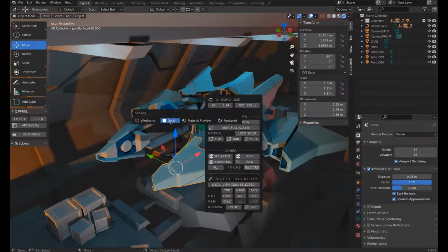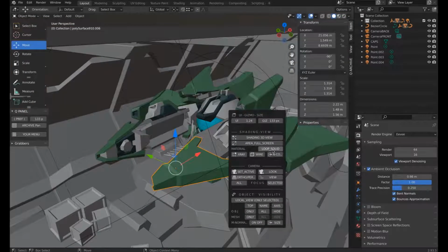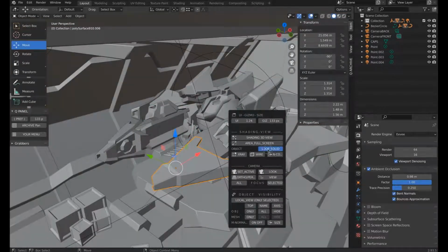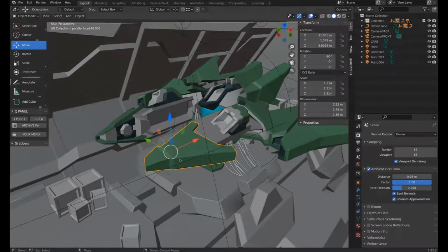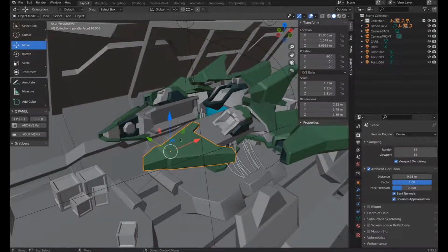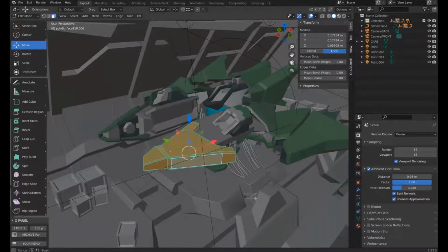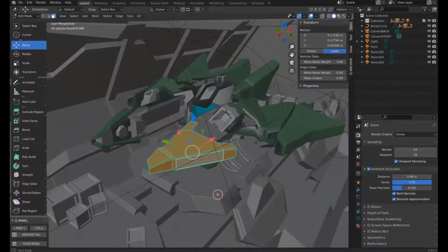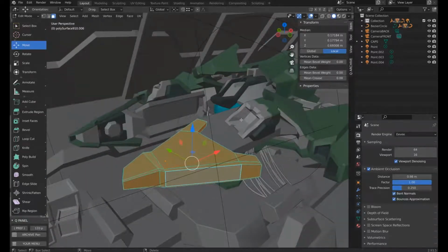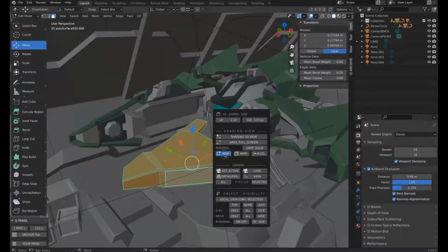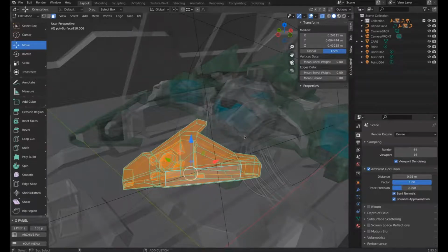Let's go back to the solid view to use the loop solid. Then we can see the X-ray. Blender lets you select only what you can see. So if you go in edit mode and try to select something, you can select only what you can see. To select both, you have to enable X-ray. And here we are.